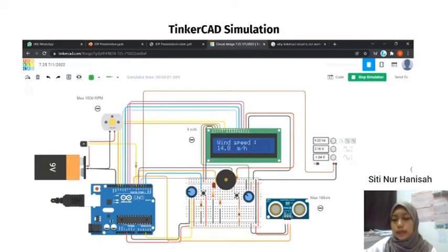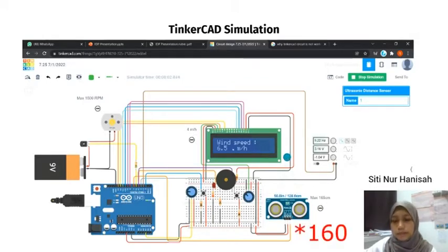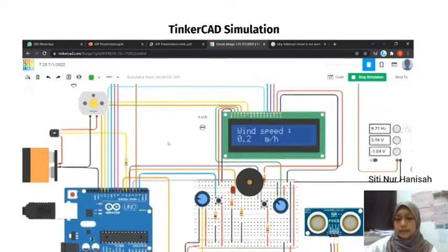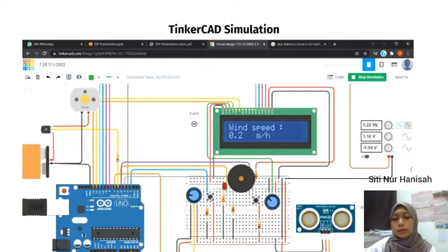The last ones are the ultrasonic sensor at the processing center, where, when the basket is lower than 1.65 meter, the motor will slow down and we will unload the basket, and a push button as the emergency button. If there is any emergency condition, we will push the button.